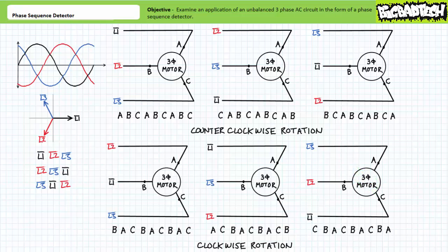The larger point being that the phase sequence established by a three-phase AC source between L1, L2, and L3 is fixed and unalterable. However, they can be applied at the point of use in any manner deemed suitable for the application. Wired in one fashion, a motor would drive a conveyor belt forward and send an elevator up. Wired in another fashion, a motor would drive the same conveyor backward and send the elevator down. Understandably, a user should have some idea of the phase sequence prior to wiring up a motor, as it is a generally recommended practice to avoid driving a conveyor backwards when you press the forward button, and it kind of sucks to have an elevator go up when you're on the top floor or down when you're on the bottom.